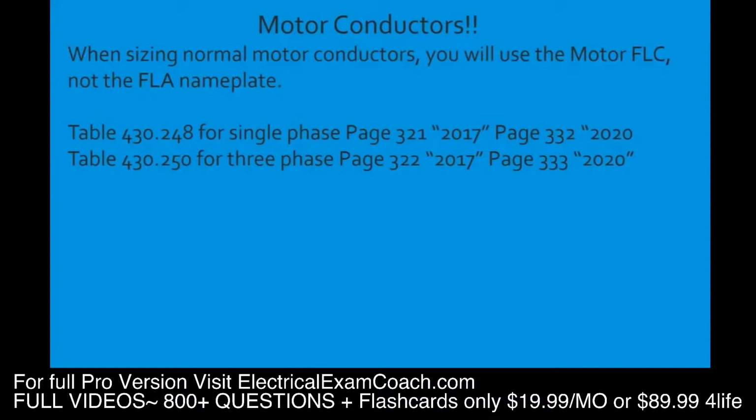When we go to read this table, we're going to read it just the same. We start on the left-hand side. It's going to be our respective horsepower. And then coming across the top are our voltages. Again, I want to warn you, make sure that whatever the question states, you choose from that voltage. So even if it doesn't make sense, if they put 230 volts on a three-phase system, just do whatever the question states. Don't try to change the reasoning there because it's very easy to do.